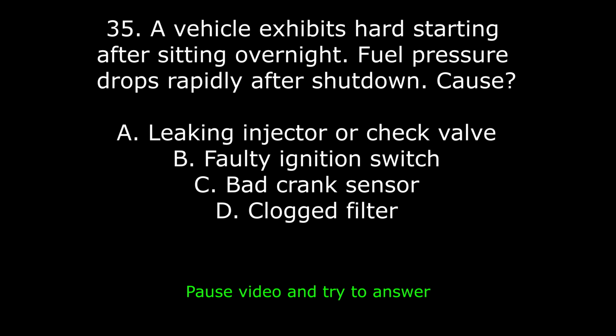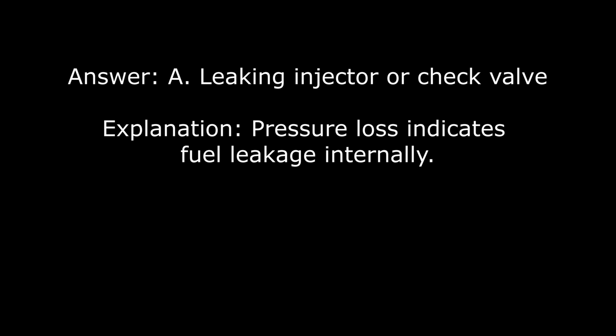35. A vehicle exhibits hard starting after sitting overnight. Fuel pressure drops rapidly after shutdown. Cause: A. Leaking injector or check valve, B. Faulty ignition switch, C. Bad crank sensor, D. Clogged filter. Answer: A. Leaking injector or check valve. Explanation: pressure loss indicates fuel leakage internally.